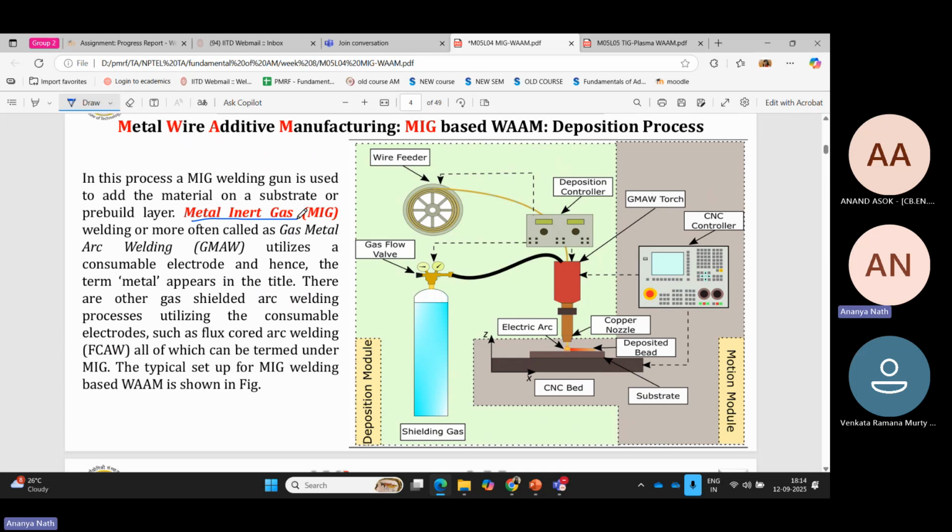So always remember, from the minus end, the electrons get emitted. And from the positive side, electrons cannot get emitted. So what happens is the material gets eroded, like the material comes out of the metal. So when you are talking about a process where you're welding, your electrode is consumable. That means your electrode has to be positive.